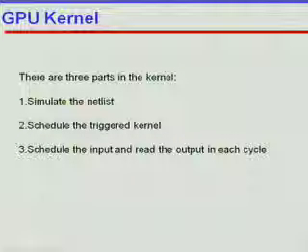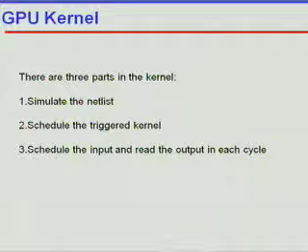Next is our kernel part. In the GPU, the running part is called the kernel. There are three parts in the kernel. First, we need to simulate the netlist. Second, we need to schedule the triggered kernel. And third, we need to schedule the input and read the output in each cycle.